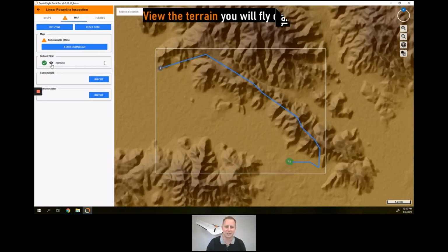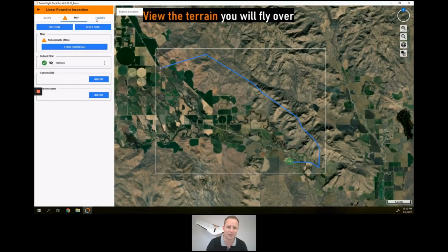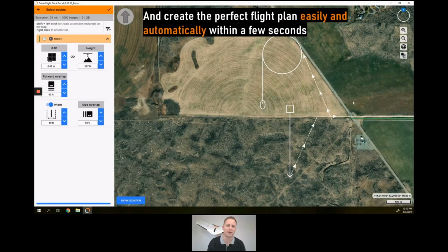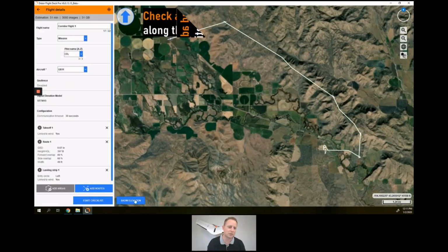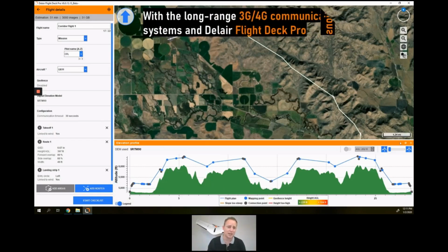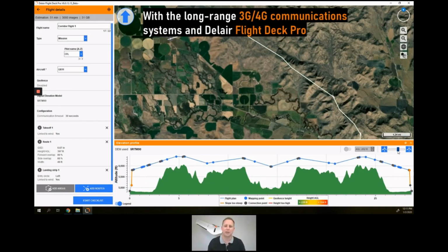And now this part is an exciting tool too. This is the linear flight planning. So here we created a corridor. You can do that by bringing in a shapefile or a KML file. You set the corridor width that you want, 50 feet, 100 feet, 100 meters, 500 meters, whatever it is, and then it will automatically plan that corridor flight, whether that's a pretty continuous line like this or if it's a branched network. You also see in the elevation profile down there that we're also editing now, because we're going through some mountainous terrain there. We're editing those waypoints to smooth that flight out.